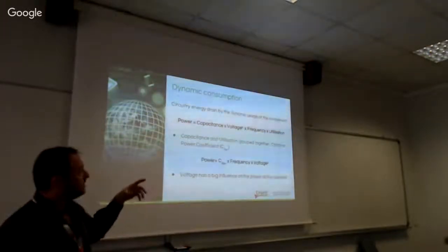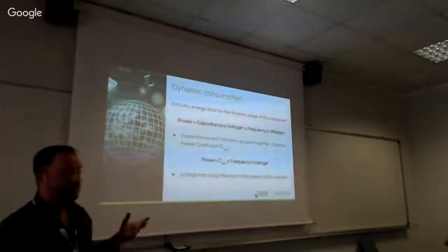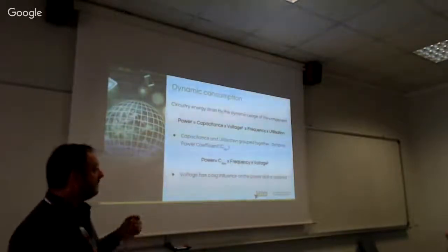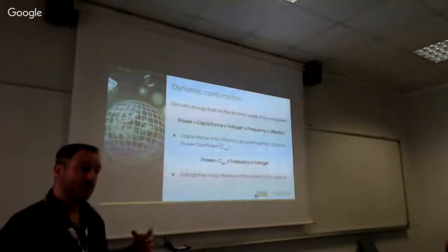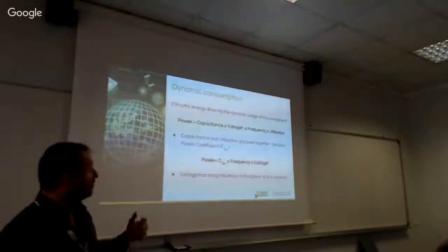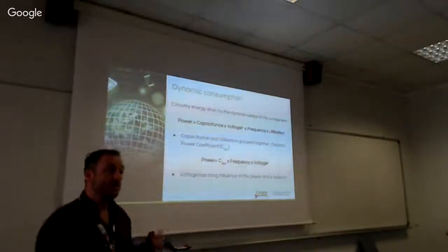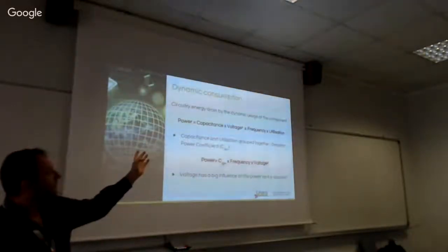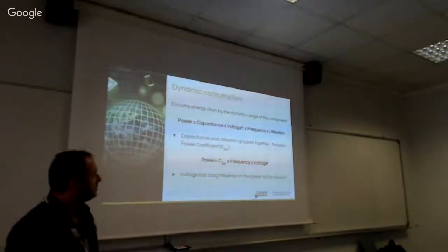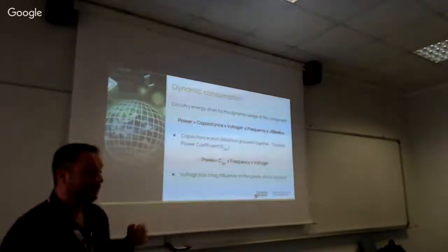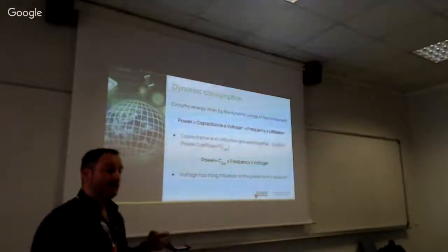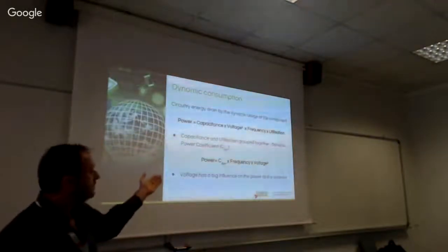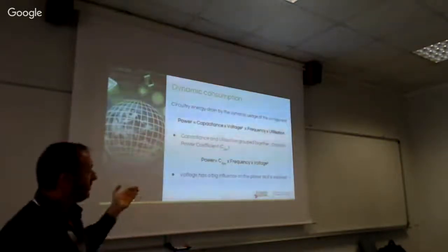These terms, capacitance and utilization, are grouped together because these values are hard to get from vendors. So in the kernel, we have the dynamic power coefficient in the DT, giving the result of this factor, capacitance and utilization. So we can compute from the kernel the power at a specific OPP by using the equation for C dynamic times frequency and voltage.